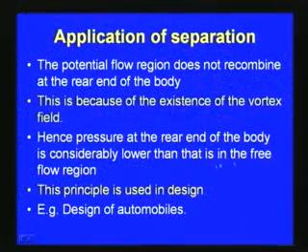Hence the pressure at the rear end of the body is considerably lower than that in the free flow region. So, after the boundary layer separation and the wake formation, or due to the existence of the vortex field, this is what happens after the separation takes place. This principle we can utilize in the design of automobiles and also in the design of various flying machines like aeroplanes and other equipment. So, these are some of the important applications with respect to the separation of the boundary layer.